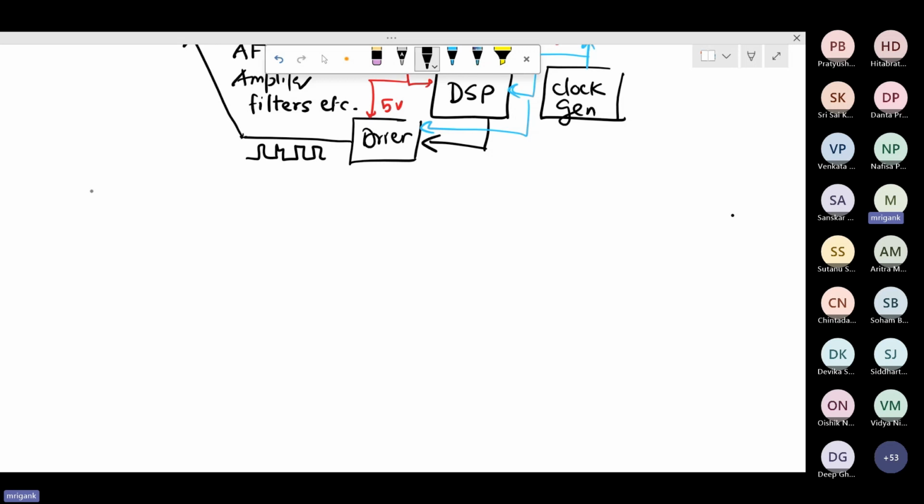For example, the ADC will require the signal that it can handle, right? So what is the signal amplitude that it is going to handle? The amplifier gain, bandwidth, the noise, because each circuit component also contributes to noise. So how much noise is allowed, how robust it should be, what should be the noise figure of the circuit. Those things we'll discuss subsequently, but these are important parts for the analog front end side, right?